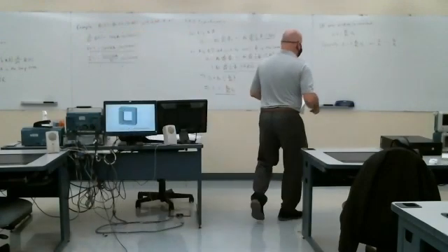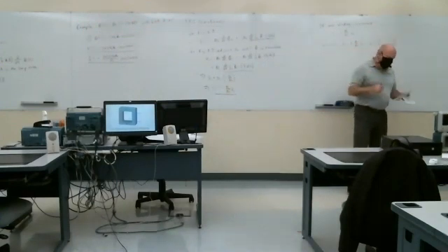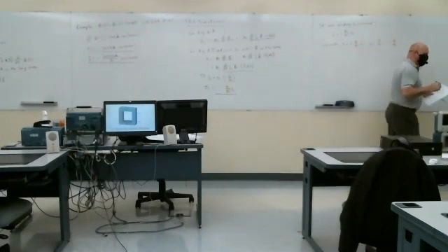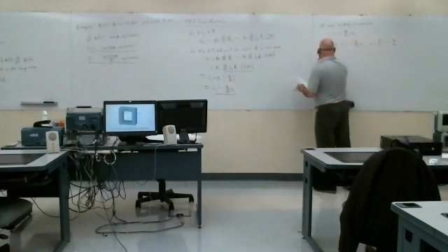Otherwise, use the minus sign. So in that particular figure, it would be the plus sign. But if either winding were reversed, or the source polarity were reversed, or the assumed secondary polarity were reversed, we would get a minus sign.